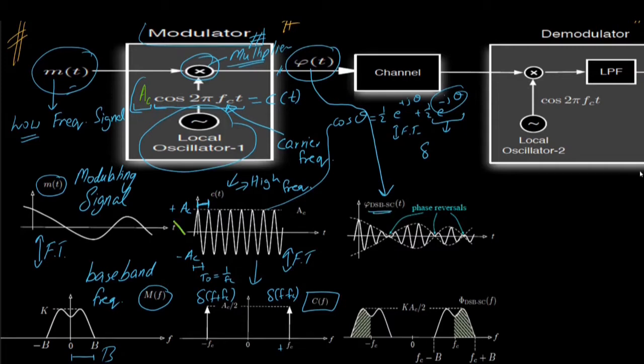If we multiply these two signals together, one is slowly varying in time and the other has a high frequency, that is, it varies quite quickly with respect to time. We would eventually get this signal, with an envelope based on the low frequency signal, and within that envelope the high frequency coming from the oscillator.